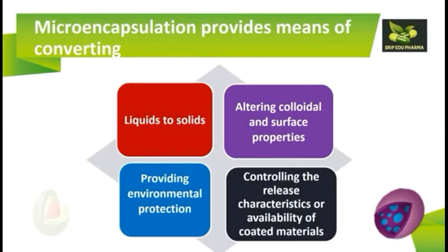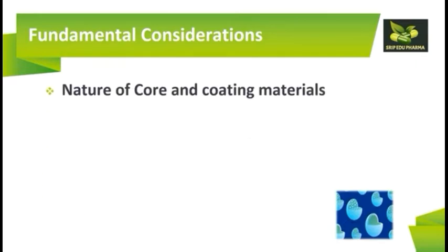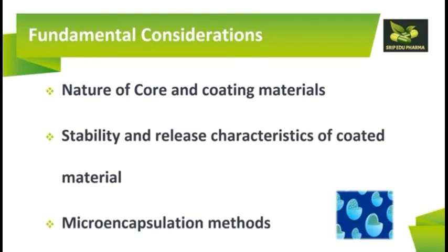Spray drying is dispersing the core material in a liquefied coating substance and spraying or introducing the core coating mixture into some environmental conditions whereby relatively rapid solidification of the coating is effected. And spray congealing is likewise dispersing the core material in a liquefied coating substance and spraying or introducing the core coating mixture into environmental conditions whereby relatively rapid solidification of the coating is effected.